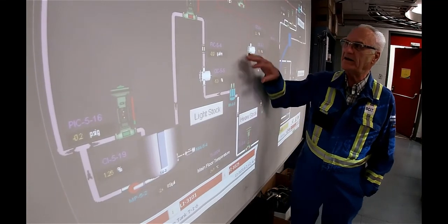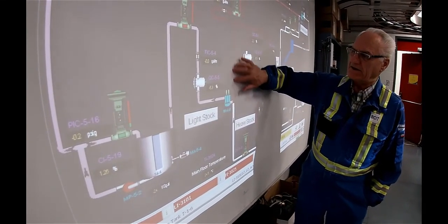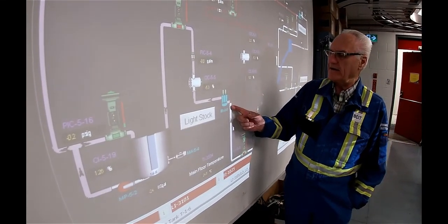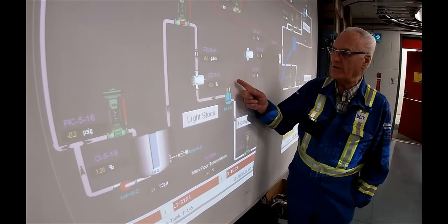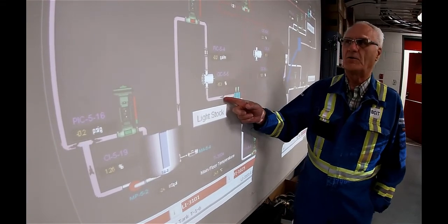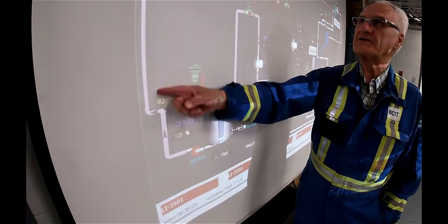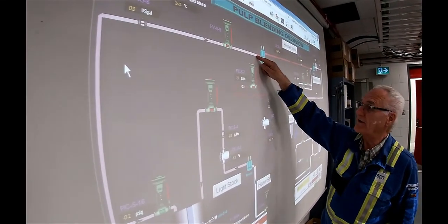Consistency meter will be monitoring that and actually controlling the addition of white water to maintain the consistency at 1.75%. And to give you some idea, if there was 37.5 US gallons a minute of stock coming in here, and 37.5 gallons a minute of water coming in here, the 3.5% stock would get cut in half down to 1.75%, which is what we're actually targeting for.